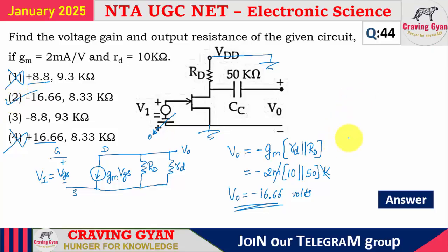What is the value of R0 you are going to get? See, if you want to find the value of R0, start looking from the V0 terminal. All the voltage sources need to be de-energized and all the current sources need to be de-energized. When V1, which is equal to VGS itself, is 0, gm times of VGS is 0, nothing but the current source is behaving like an open circuit.